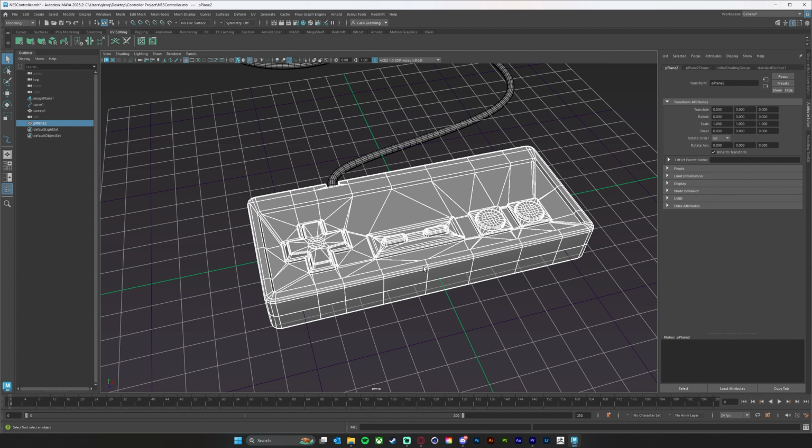You're going to be working on your model and fixing your model a little bit as you're doing the UVs, because otherwise you're going to get to certain steps that you just can't do if you have n-gons or non-manifold geometry. A lot of times doing UVs will expose a lot of issues that you weren't aware that you had. And then you have to put your UVs on halt, fix those issues before you come back to working on your UVs again.